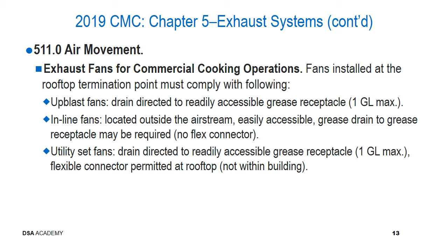In the event that an inline fan is installed in this type of ductwork, it's required to be located outside of the airstream, easily accessible, and additionally a grease drain to a similar grease receptacle may be required. But in no situation is a flex connector permitted in an inline fan application.